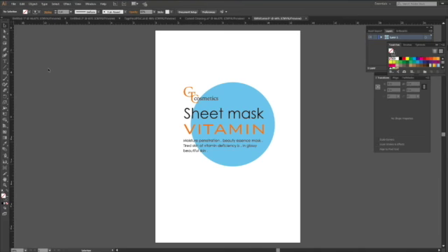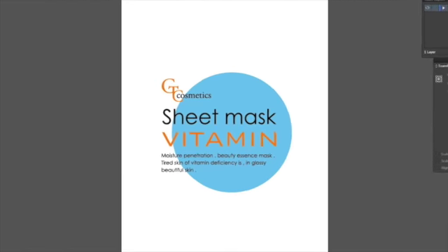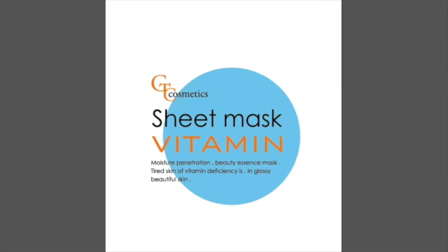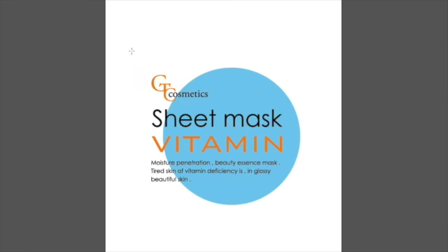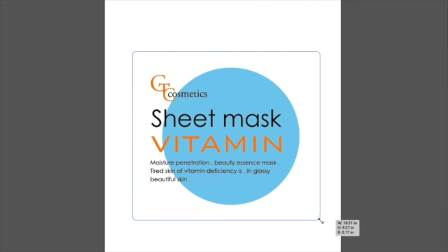The first step in the print and cut process is to create the cut path. Keep in mind that the cut path should be created after the design is complete and before creating the registration marks. A cut path can be any shape with a thin line and no fill, such as a square, circle, or any other shape such as a square with rounded corners.